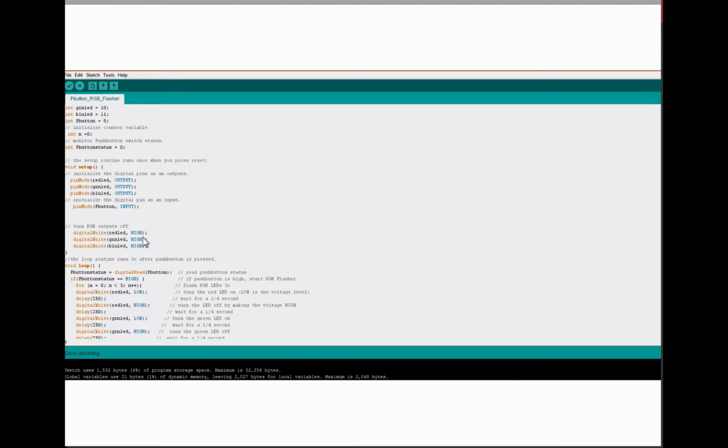So in this case, I'm turning it off because the way the LED works, we don't want it on initially. So I'm telling the switches right here to turn off the LED by making this output a high, okay? And the high is a binary level, and the binary deals with bits 1 and 0, or in terms of voltage, it's either 0 volts or 5 volts. So I want it to be off, and by setting up the way you see here, that's how we're going to turn it off, okay? We're going to put a high or a binary 1 on that little LED, and it knows, okay, I'm not going to accept any electrons. So those guys are off initially.